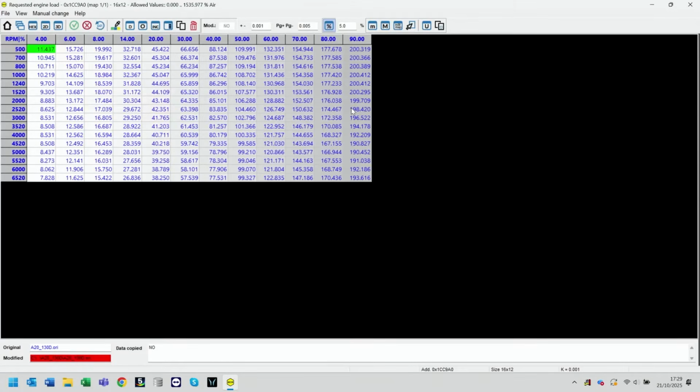Effectively, if your boost goes above your request, it's an early lunch, everything turns off, it backs everything off because the job's been done. It's achieved its target. Suddenly the power drops, panic sets in, winds the actuator back up, trying to deliver the boost, and you end up with a horrible oscillation, this sort of on-off feel to the power. So we need to raise our request. If we agree that our new target is going to be 190% of cylinder filling for our limits, well then our request needs to sit above that.